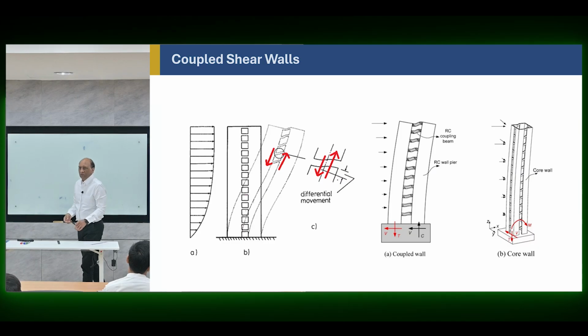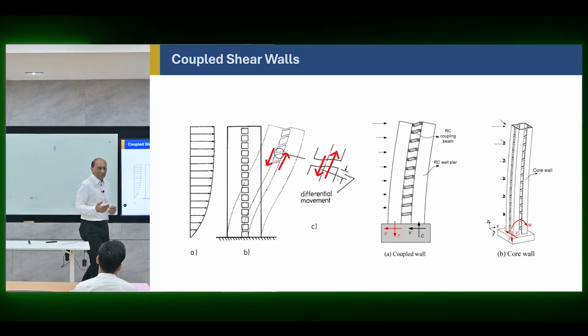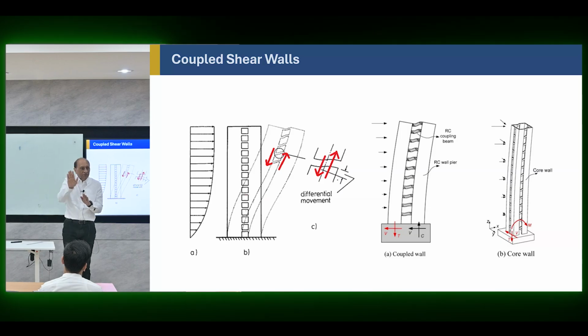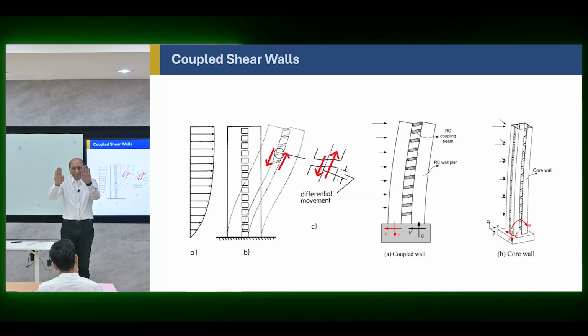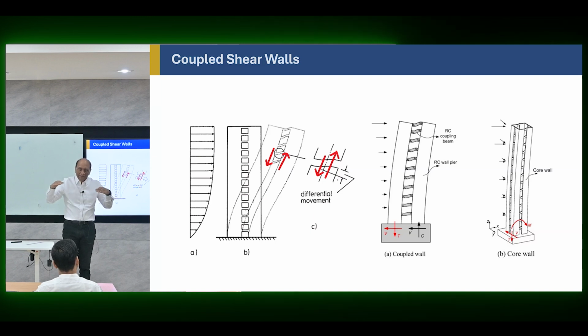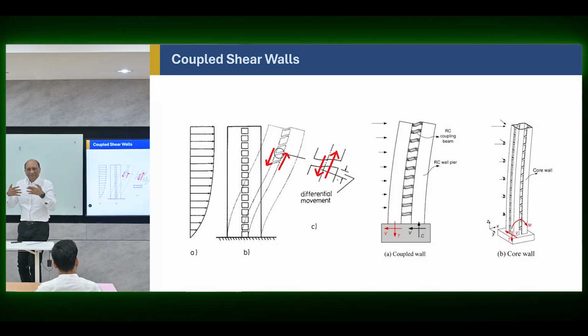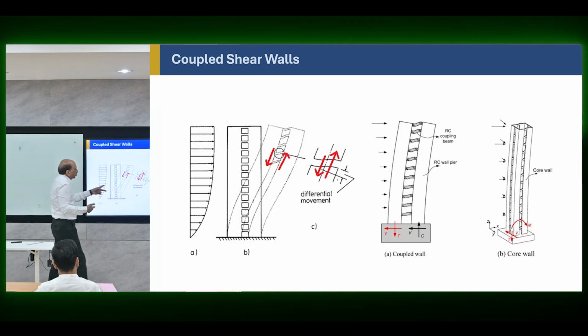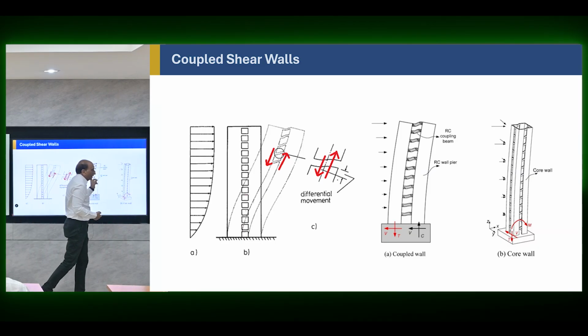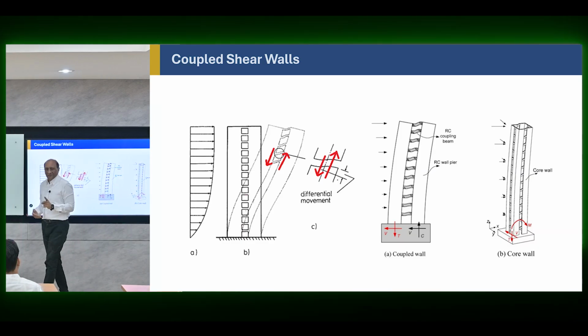So now this coupling effect is not the same as shear wall frame interaction, because that was just because of the shear mode and the bending mode becoming together, and that will produce forces in the floor, which is connecting them. But this is going to produce shear and bending moment in the elements that connect those two, whether it's two walls or a wall and a frame, will have the same effect, right?